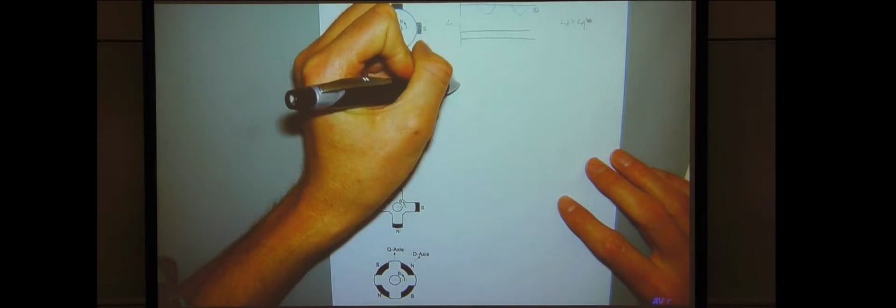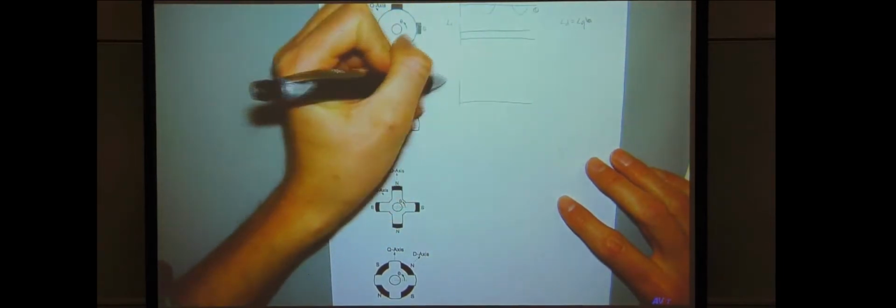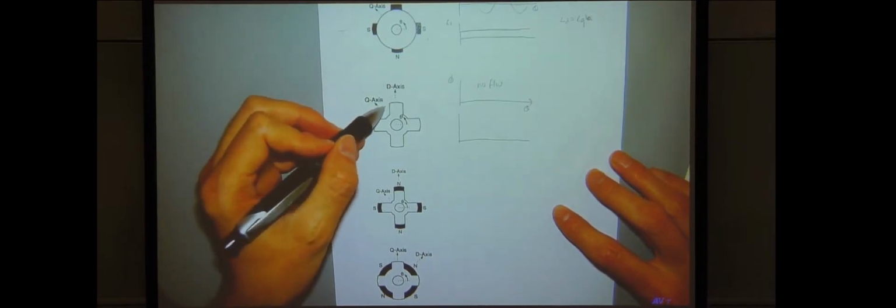So if you now look at this rotor here, and I think we talked about this in the electric machines analysis class, then clearly there's no magnets on here, so there's no flux due to the rotor, which is not interesting. But then if you look at the d-axis relative to the q-axis, there's a clear difference in the saliency.